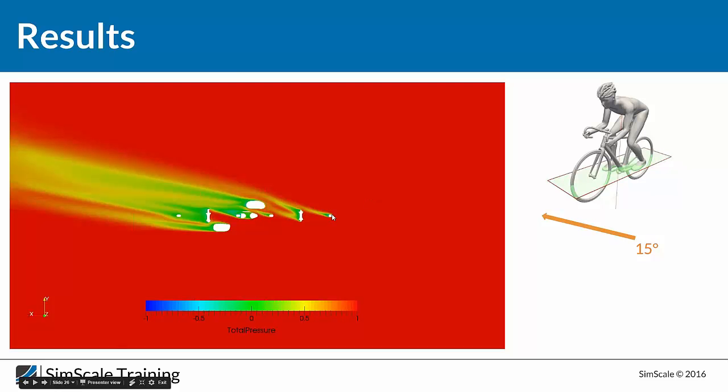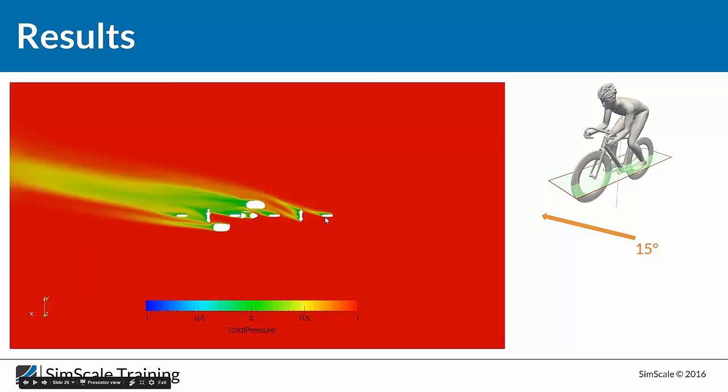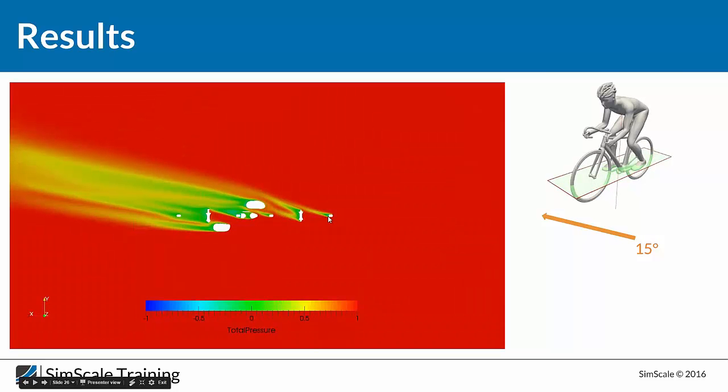And we can see here for the small, thin tire that the flow is highly detached, and there is a strong separation over here, and the recirculation as well, and also for the rear side of the front tire. But if we jump to the next one, we can see that there is separation, but if we take a close look, here the separation started a bit earlier compared to this one. So this one, the separation is not really earlier like the previous one.